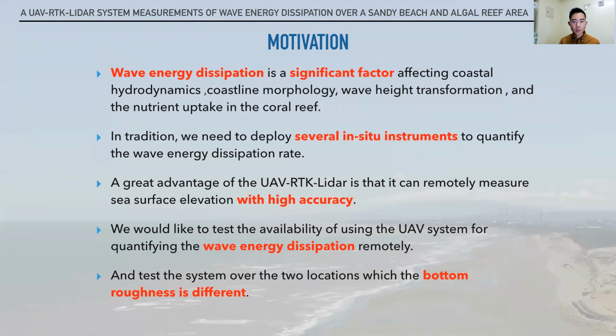Traditionally, we need to deploy several in-situ instruments to quantify this quantity. In this research, we would like to test using a UAV-RTK LiDAR system to measure the wave height and to calculate the wave energy dissipation. We also would like to test the system to measure the dissipation over two locations, which are a sandy beach area and an algal reef area.